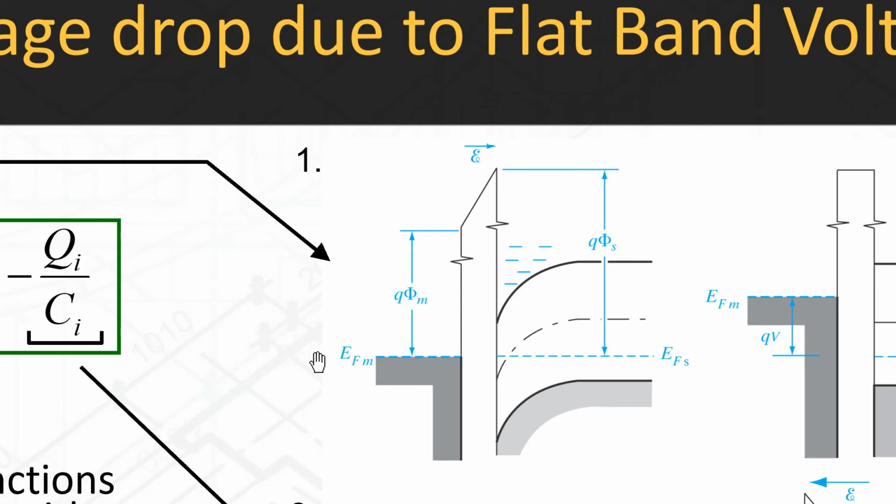But this is the E0 for the semiconductor, and this is the E0 for the metal, and they're at very different potentials. As a result, there's a bending in the band diagram, in EC and in EV, and that's what causes this effect. So you can actually end up with an inversion channel even when you don't have a potential applied to the gate.